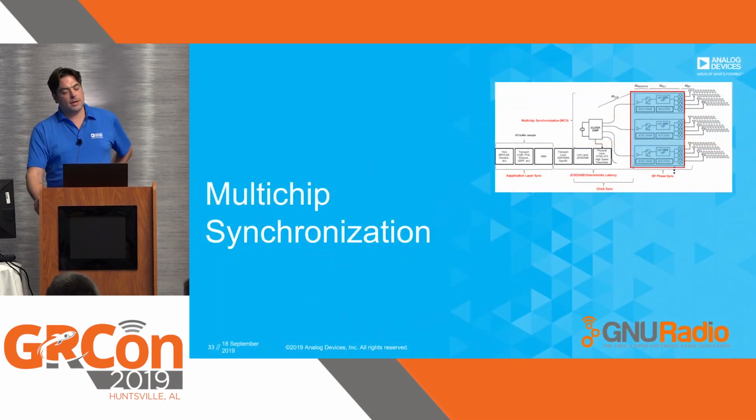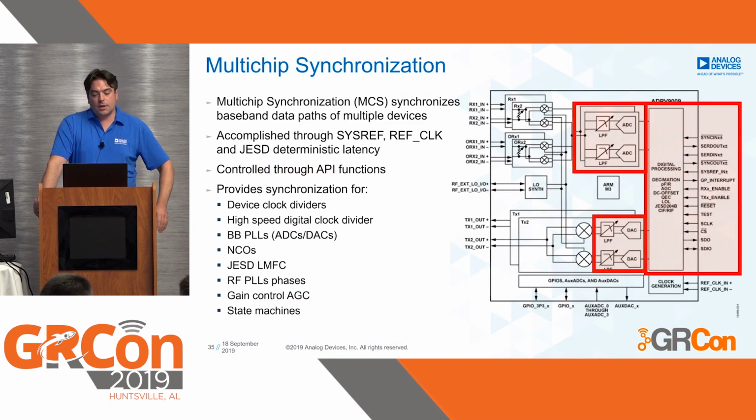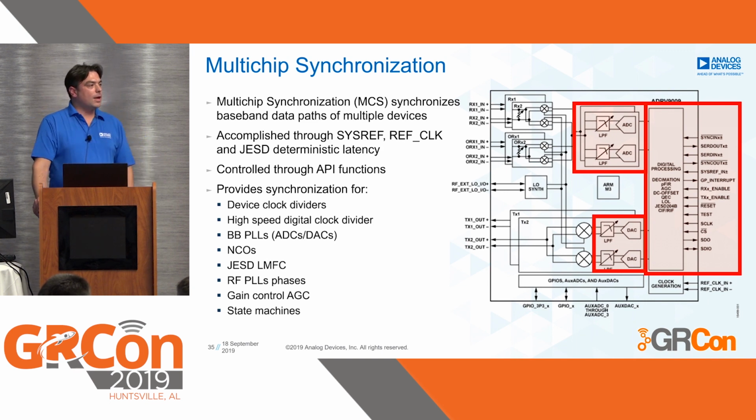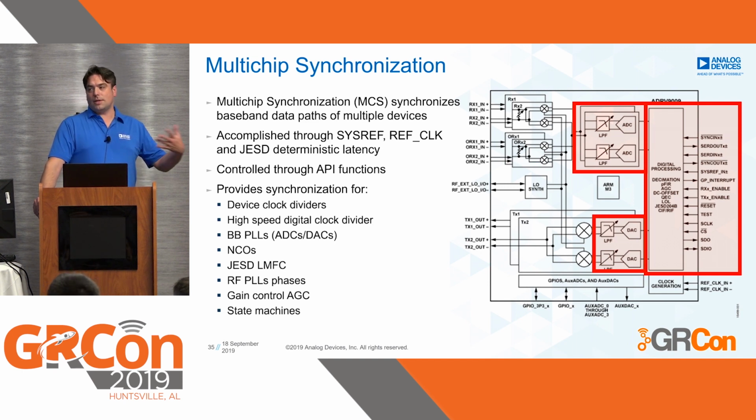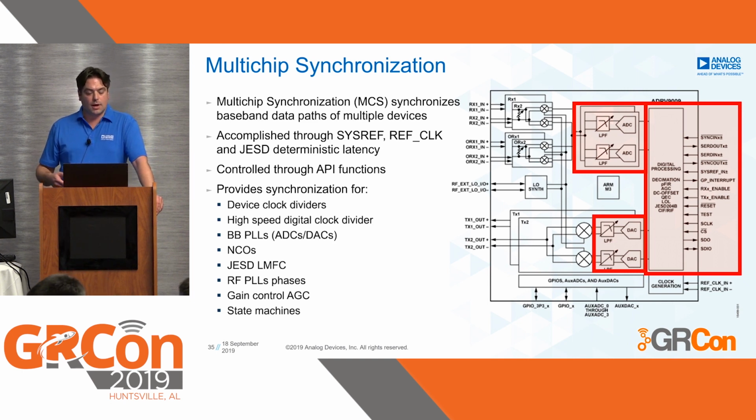The next thing in synchronization is multi-chip synchronization. This is where we synchronize the baseband signals, or the baseband path, of multiple transceivers. It's also using the SysRef and the ref clock, but this time it's not synchronizing the JESD link, it's synchronizing the internal dividers of the chip, the NCOs. All the state that's in the chip needs to be synchronized if you want to synchronize multiple parallel instances in your multi-channel system.